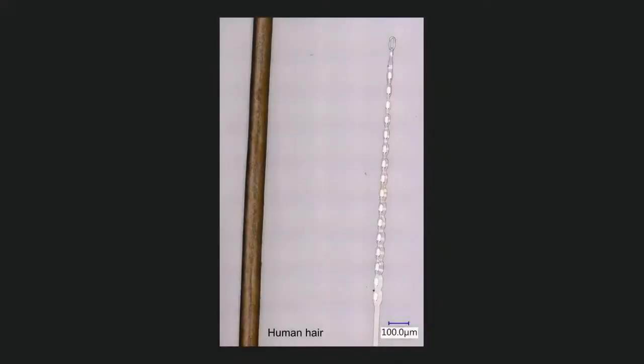In our current design, we have a 3 metal layer process that results in a 5 micron thick and 10 to 40 micron wide probe. To give you an idea of how small this is, red blood cells have a diameter of about 8 microns. And an average strand of hair is about 100 microns. Yet in this small footprint, we're able to fit our electrodes, our wires, and the insulation for each of those wires.